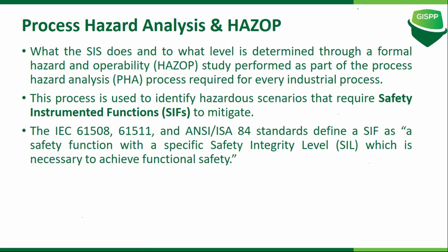Like I talked about data center temperature. You will provide me a certain value of temperature: 21 degrees centigrade. If it reaches this, turn on this process. If it reaches 24, turn on this step. Every action is taken on certain parameters. So if I corrupt a process and tell that controller, on 28 degrees send an alert to the person sitting in the monitoring unit, it will be too late. So I need to protect those values as well.